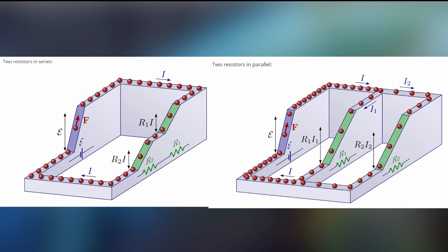But what happens to the total amount of current that flows through the whole circuit? The total amount of current actually increases. Remember, in the series case, the total amount of current decreased because we increased the total resistance. Well, in this case, we've actually reduced the total resistance by putting in more light globes. Now, this might sound weird. How can we have reduced the total resistance this time when last time we put in an extra light globe, we increased total resistance, but this time we've reduced it?